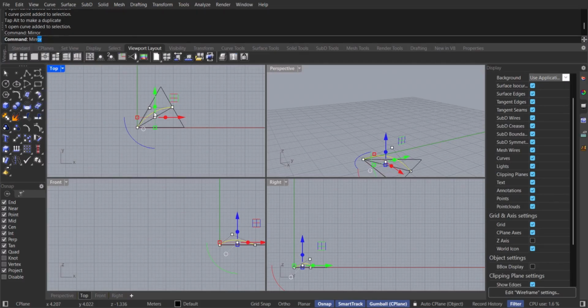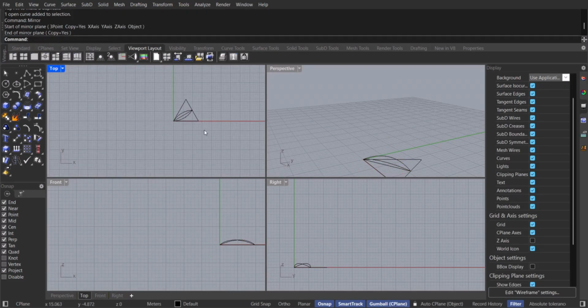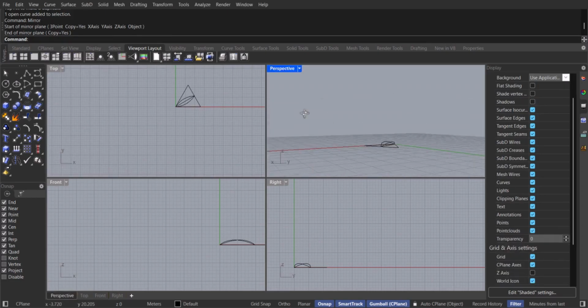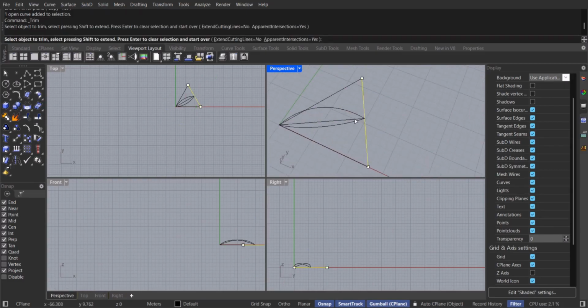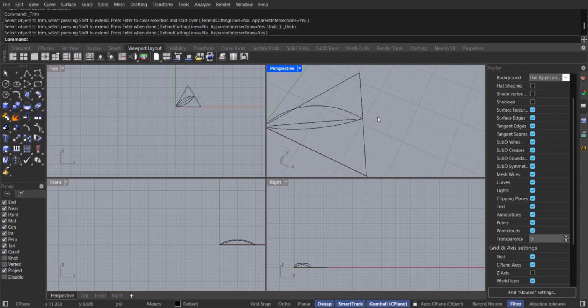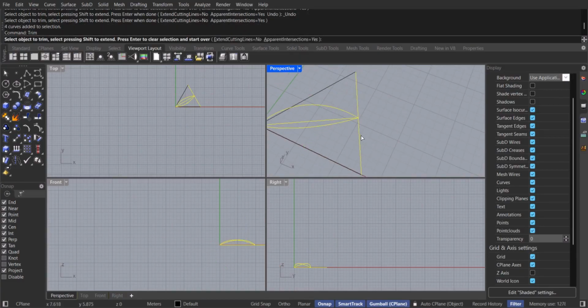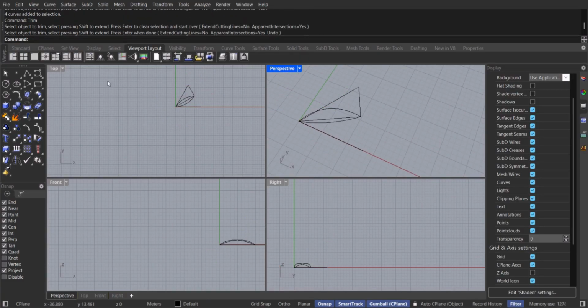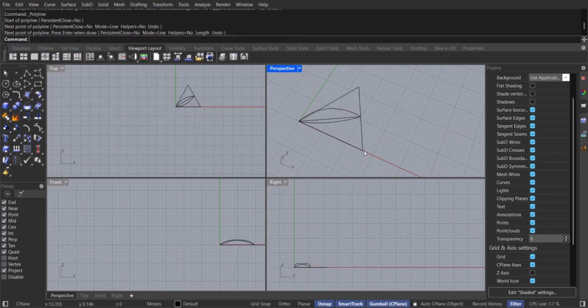Now I mirror it for the other part to see what it's gonna look like, just to see the future picture of it. And I think it's perfect. Now I want to divide all the lines. I don't want any connected lines between the two parts, so I can select all the lines and write the command trim and trim this part because it's one line. I want it to be 2 lines, and I can add another line.